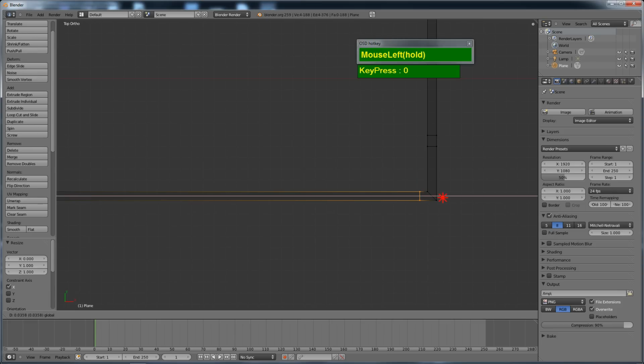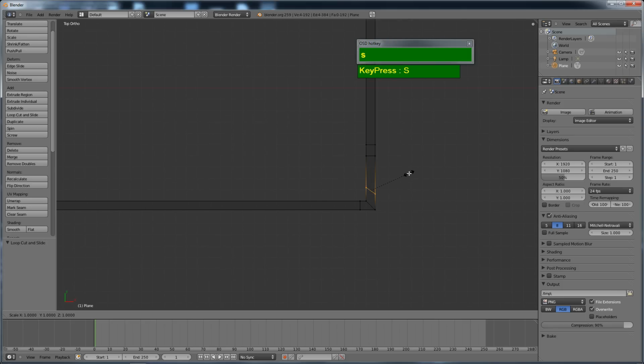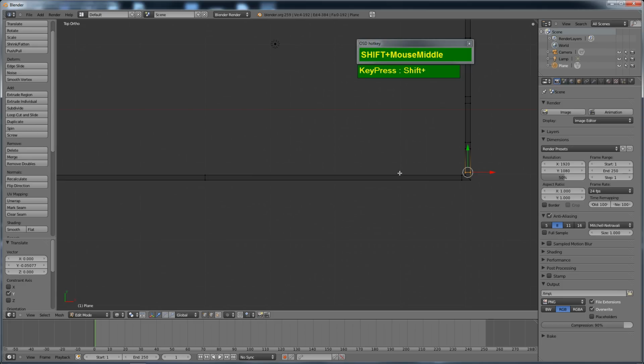Now what about this loop here? If I press Control R and insert an edge loop here, I need to flatten it along the y-axis. So you press S followed by Y and then 0. Now it is flattened. So once you have these two perpendicular edge loops, whatever edge loops you insert in between will be parallel. So you can use it to create your doors and windows.